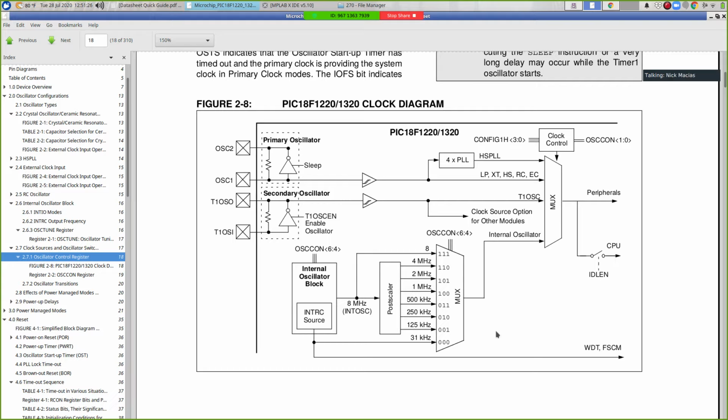And in a typical computer, there's software registers that you can modify to control how fast your CPU is clocked. And if you play around with overclocking, that's really what you're doing, is adjusting these multipliers and dividers to take this base frequency and use it to generate different frequencies from what was originally intended by the manufacturer.